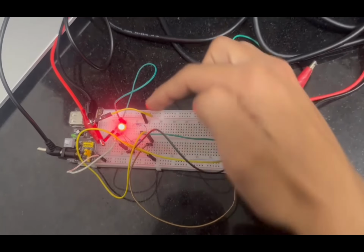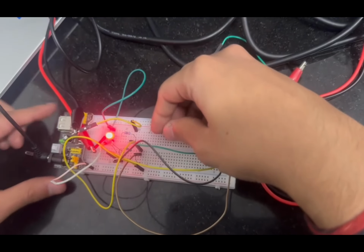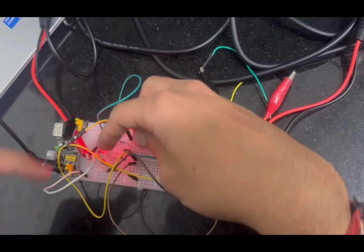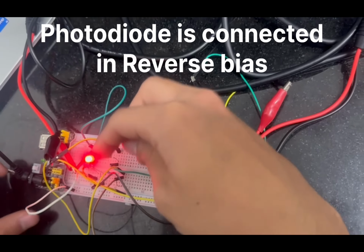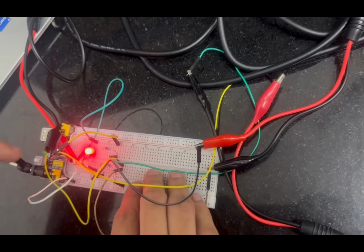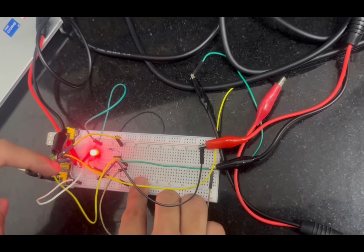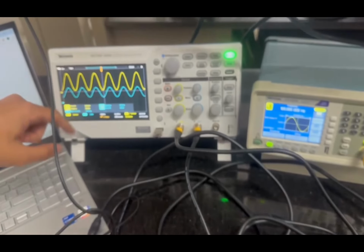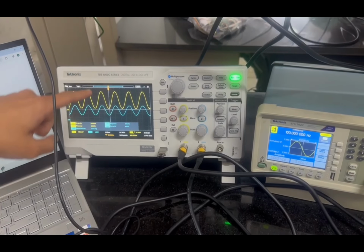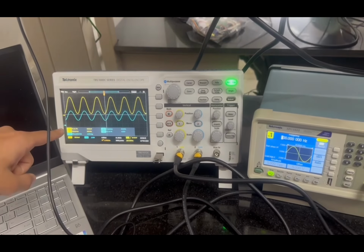So now this is the LED, which is the input part from which the signal is generated, and then we connect the resistor in series with the LED, and in front of it we connect the photodiode in such a way that the maximum light lands on the photodiode. Then we give the 5 volt input from the breadboard module to the photodiode and take the output out of the photodiode to the oscilloscope. This is the oscilloscope. We give a direct connection also from the signal generator to the oscilloscope, which is the yellow one, and one signal is passed from the photodiode to the oscilloscope, which is the blue one.